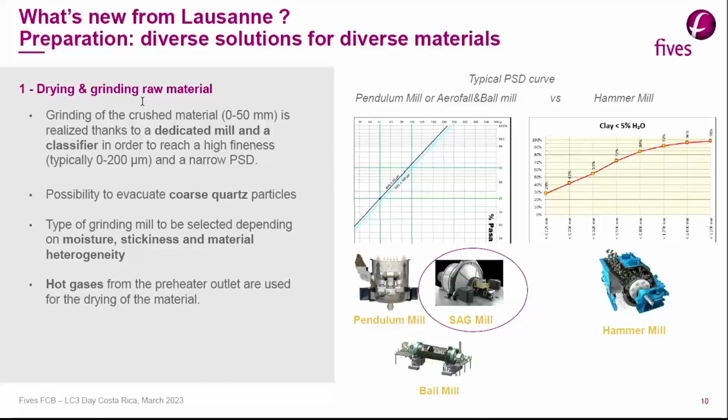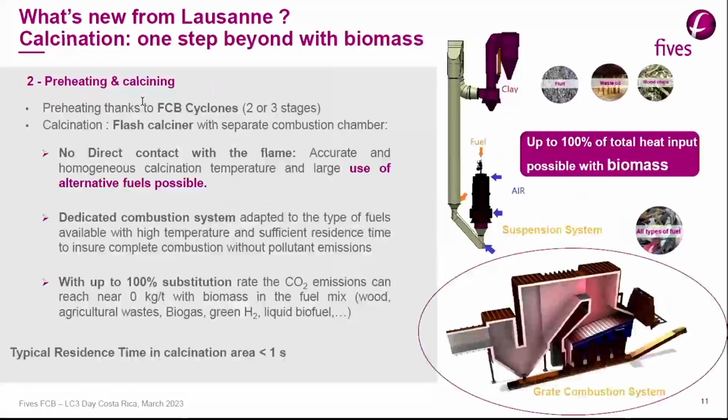The choice of technology will depend mostly on the clay type, the clay humidity, and rheology. We compare here with a hammer mill, which will, on the opposite, have a much wider particle size distribution and will not be so accurate afterwards for the calcination.